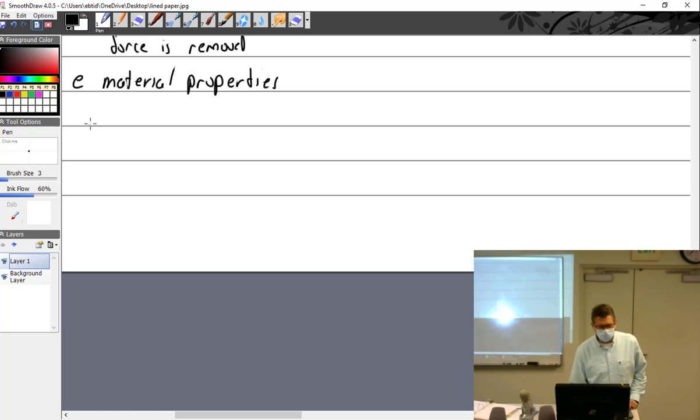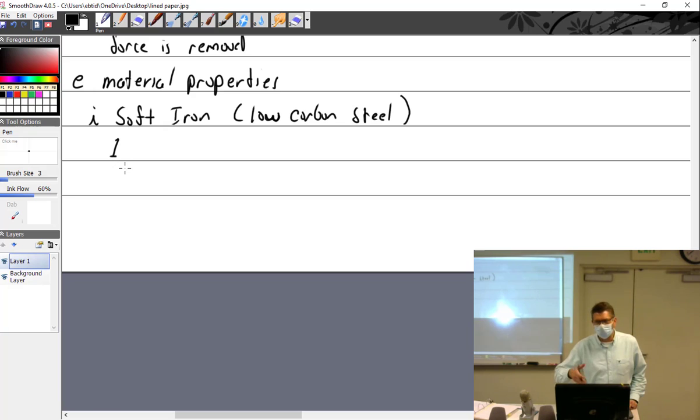All right, soft irons. Well, if you get hit in the head, there is no such thing as a soft iron. But that is to say low carbon steel. And you would think, well, it's an aircraft. Why would you ever use a low carbon steel? Why would you use soft stuff? And why not go for the best? Well, because sometimes you want things that are a little bit more bendable rather than breaking. So the harder it gets...